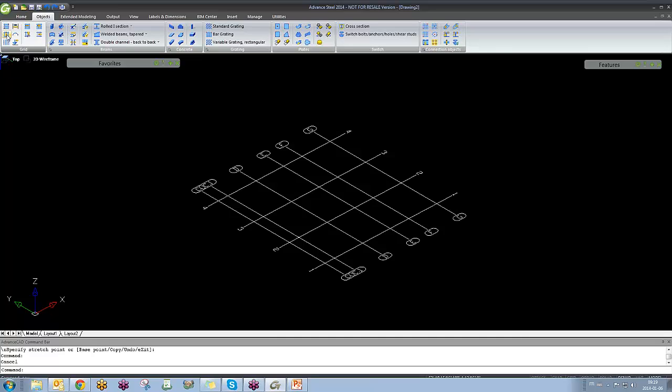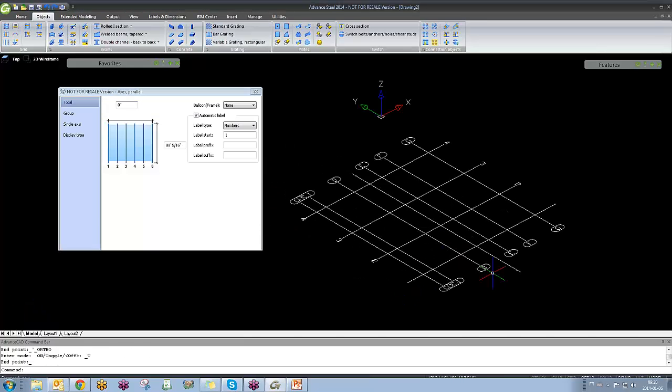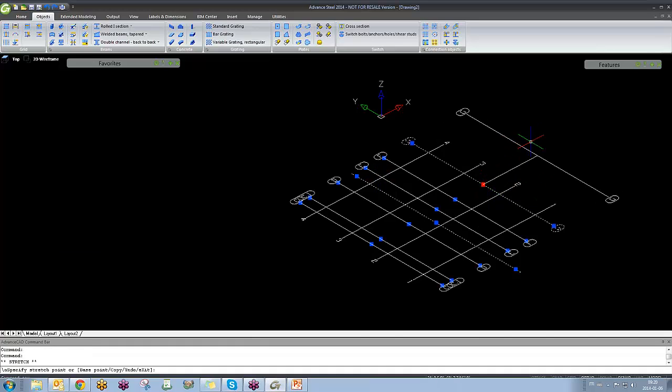A single grid line. We have in here single axis. We have this option, single axis. Just click here in ortho mode, and here it will add it. This one you will be able to snap and all that stuff. But if you move it to extend it, not.